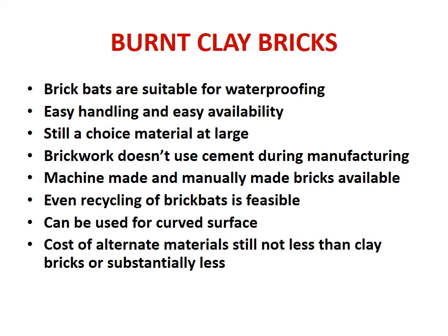So in fact that is the status when we are using alternates of burnt clay bricks. So one has to analyze all materials, and recycled CND waste materials are not available all over the country. That is another thing. Though burnt clay bricks are available almost all over the country, strength is to be found out, and then a decision is to be taken. So the project manager should take the decision as per the availability of materials and their pros and cons.